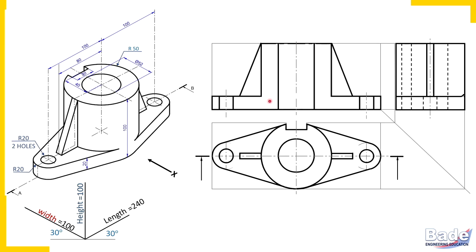Now, because of the cutting, new surfaces are getting created. We should draw hatching lines on the surfaces. Now try to understand. This small rectangular surface here, it is a newly generated surface. It is a portion of the base plate. This L-shaped surface, that is a newly generated surface. Now the triangular plate here, as I told you, is assumed uncut. So no hatching lines here.